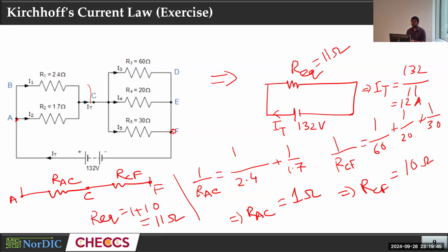Are you good? There is one tip for identifying which resistances are connected in parallel and which are connected in series. When resistors are connected in parallel, all of those resistors will always be between 2 nodes. So if we count the number of nodes related to those resistors, they should always be 2. And for series, that should be more than 2.